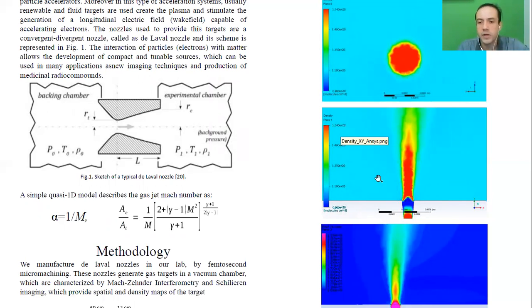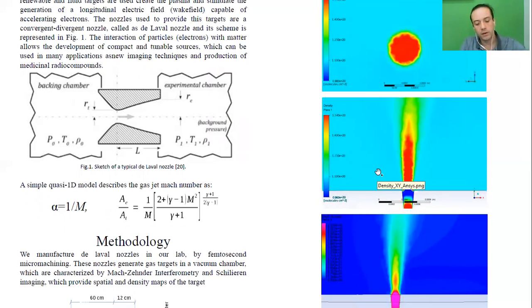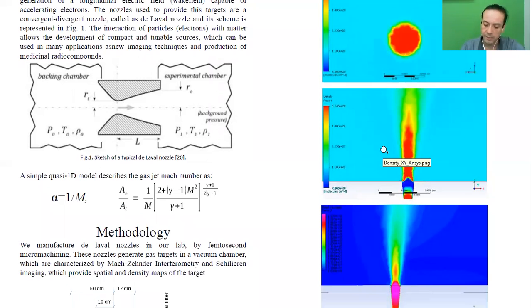Some inhomogeneities in this figure are simulation artifacts because of a non-ideal discretization of the space, due to an academic license that has a limitation on the maximum number of nodes and elements of the grid. This characteristic results in a simulation that does not describe exactly the physical system.